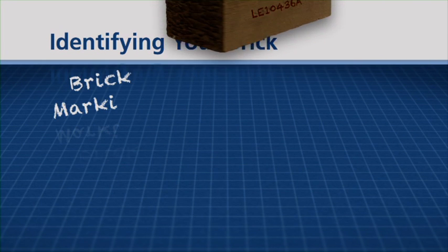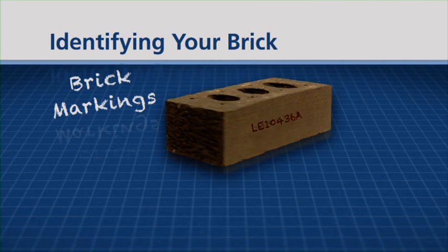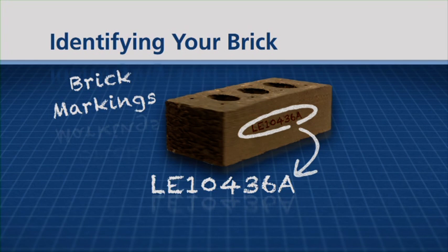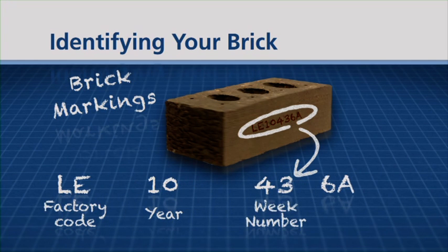To help identify a brick, you may also sometimes find markings on either the back of the brick, on extruded, or in the frog, machine moulded. This information may show a batch number, the date produced, or with frogs, it sometimes has the factory or company name or initials embedded.